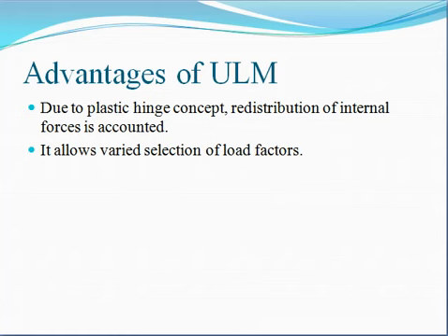This is the advantage of the ultimate load method. Now, second is it allows varied selection of load factors. Now, see in case of WSM, the load factors or factors of safety depend on the sections, that is being column, short column, long column, connections.